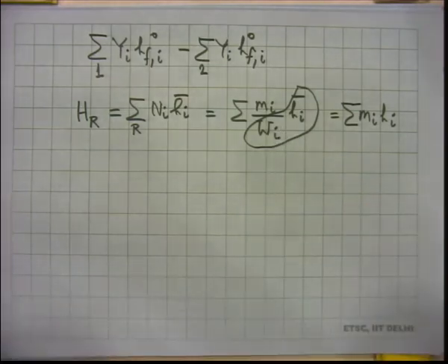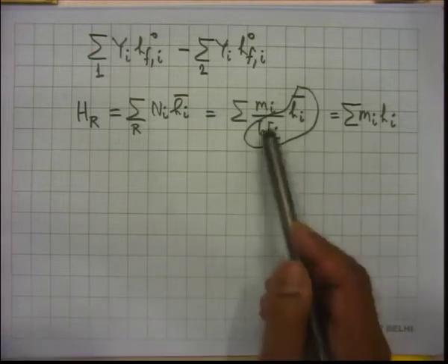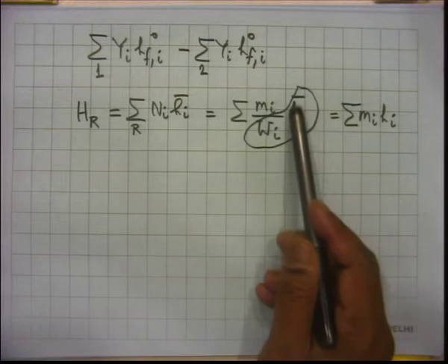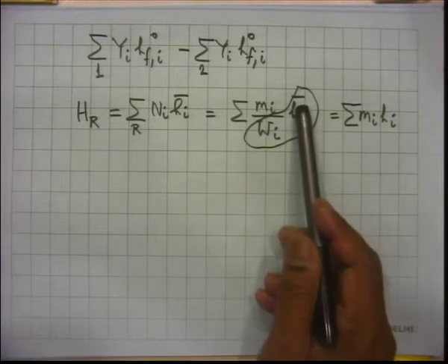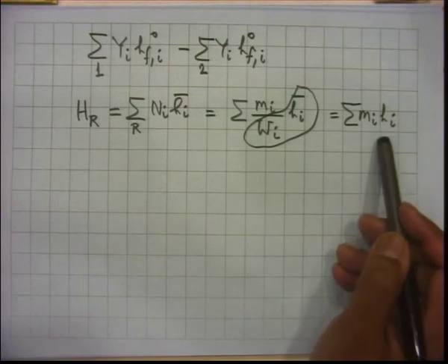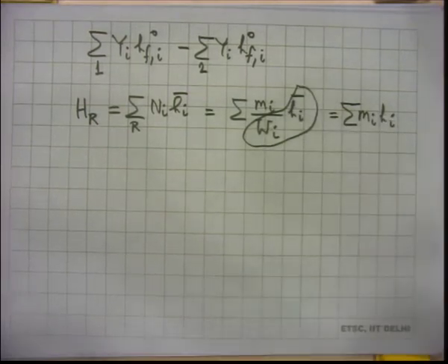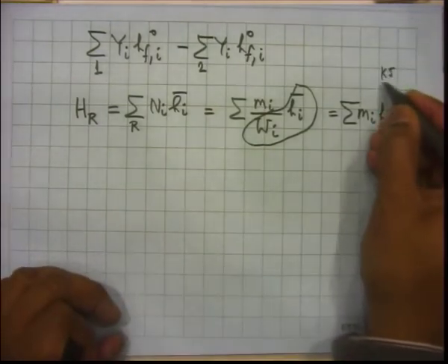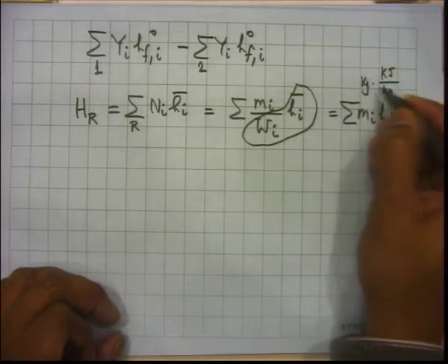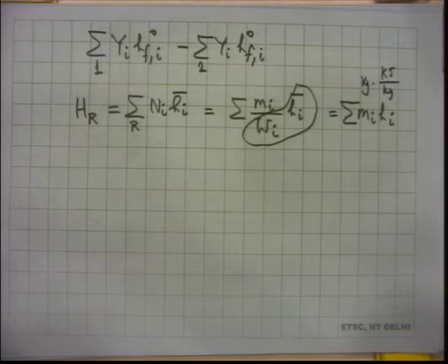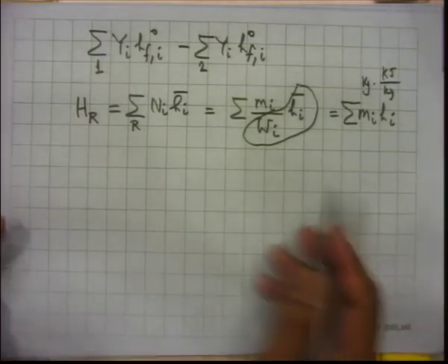See, this is, let us say, WO2. Suppose you are talking about oxygen molecular weight. Oxygen molecular weight, what do we say? It is 32 kg per kilomole. Okay. So that kg will come with the kilojoule value of Hi. So it should be able to give you kilojoule per kg of the ith species, which we are calling hi. Correct? That is why this is hi and this is Mi. Okay. So this is kilojoule per kg and this is kg. Both the kgs are actually kgs of that ith species. Okay. So we get this, and